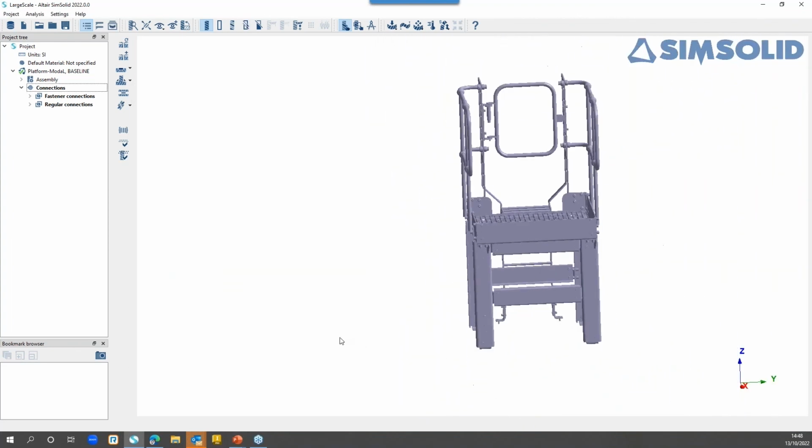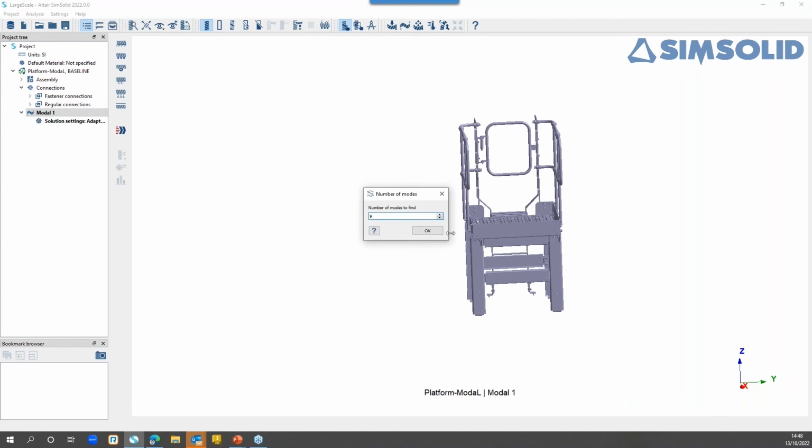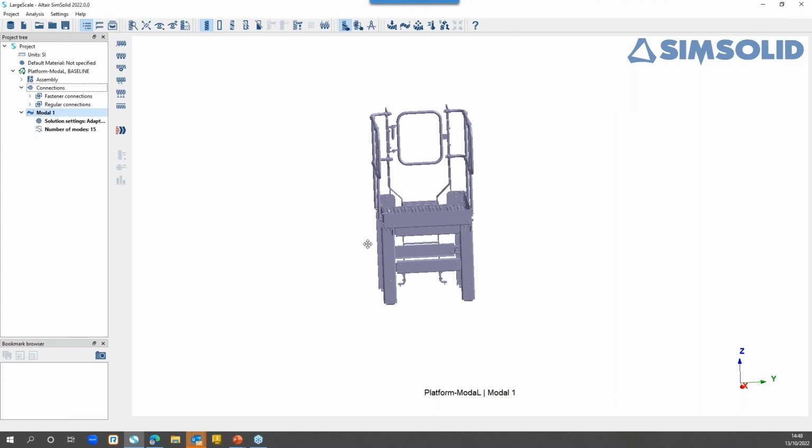And now I'm happy with that, I think. I'm going to check if there are no disconnected groups. Okay, that's fine. One of the things you can do in Nastran, and it's also in Inventor Stress, if you have a large model, is basically run a model analysis like I'm going to do here, to check if anything is not fully connected. So you can do this also in Nastran and in Inventor Stress.